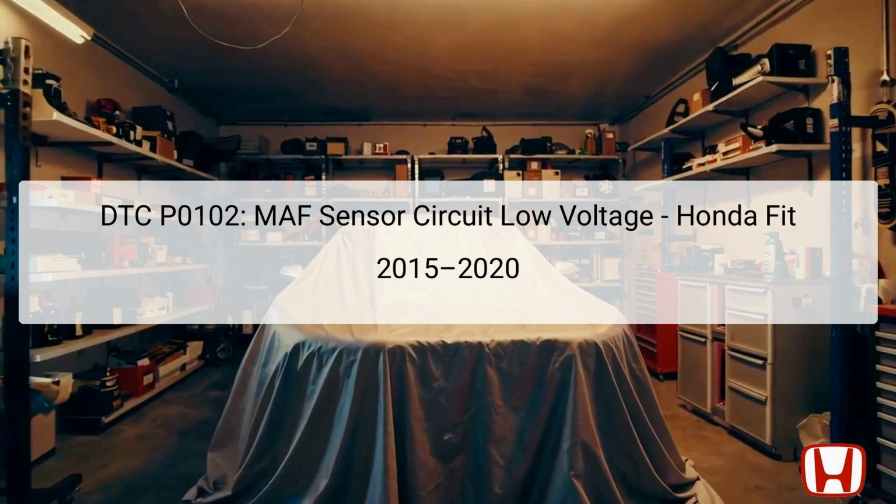This code applies specifically to the Honda Fit models manufactured between 2015 and 2020 and is commonly tied to issues with the MAF sensor or related wiring. The MAF sensor is usually located in the intake duct, close to the air filter, allowing it to accurately gauge airflow before it enters the engine.